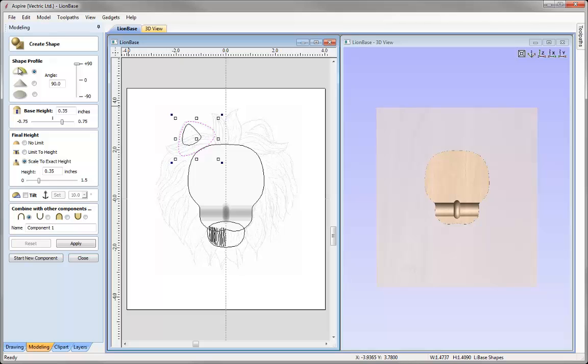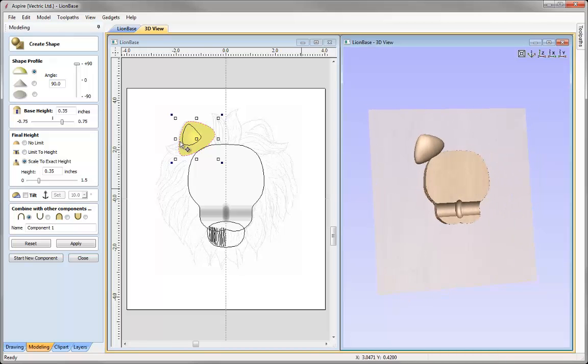In this case, I'd like to use a curved or round profile here. So working with a natural shape, it's best to use this profile. And then for the angle, I'm going to up that to 90 degrees. We can see how that looks there. I'm just going to use this option here to merge. That way it will blend in to the current model that we've got there.